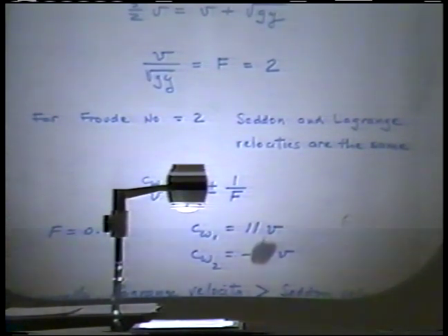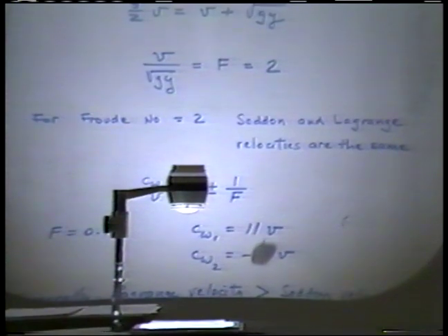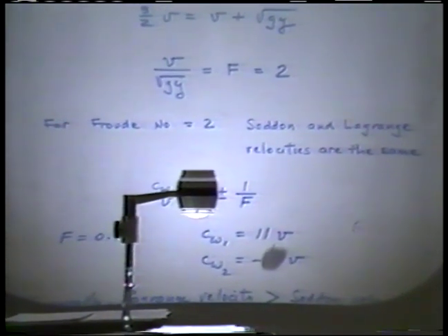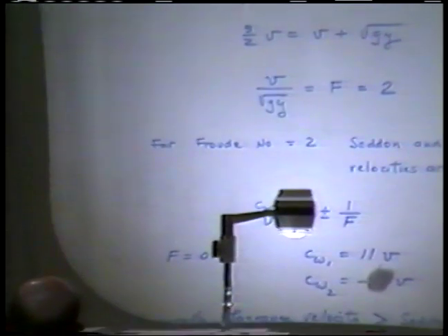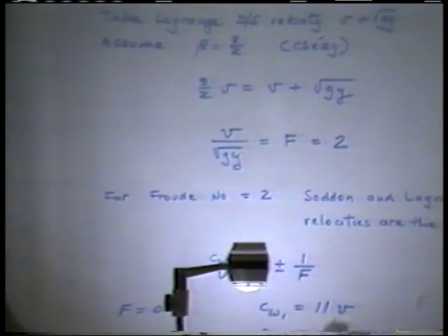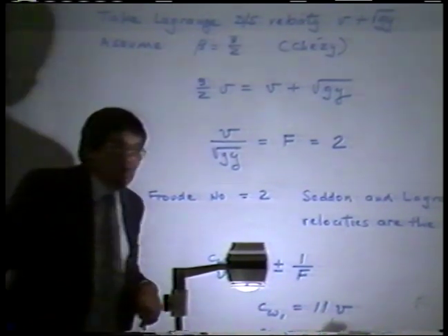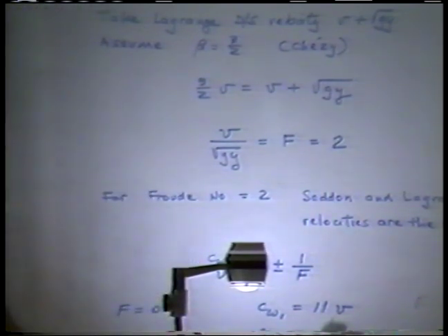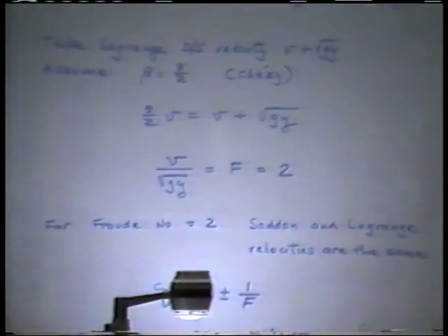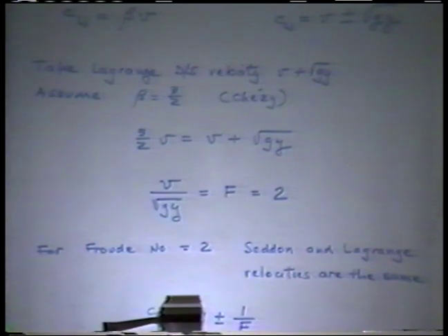We conclude, based on this, as well as other analysis that I will have a chance to refer to, that for the Froude number equal 2, which most of us like to stay away from, don't they say in the design literature that you ought to stay away even from Froude number equal 1, that you should not approach the Froude number equal 1 because it causes instability, let alone 1.5, which would be the equivalent in the Manning formulation to this 2 in the Chezy formulation. So we do like to stay away from the design standpoint from these high Froude number flows.